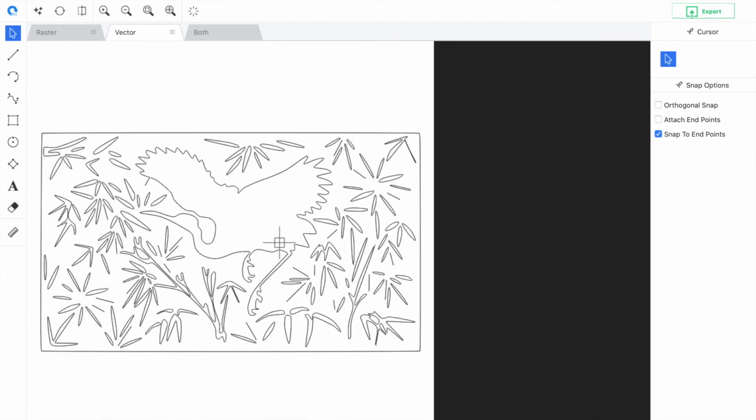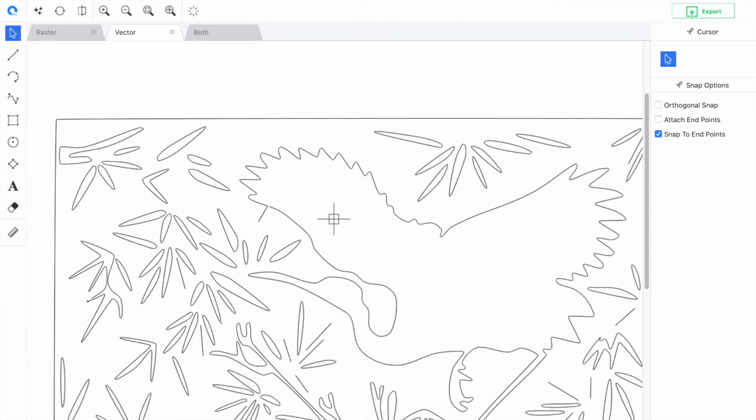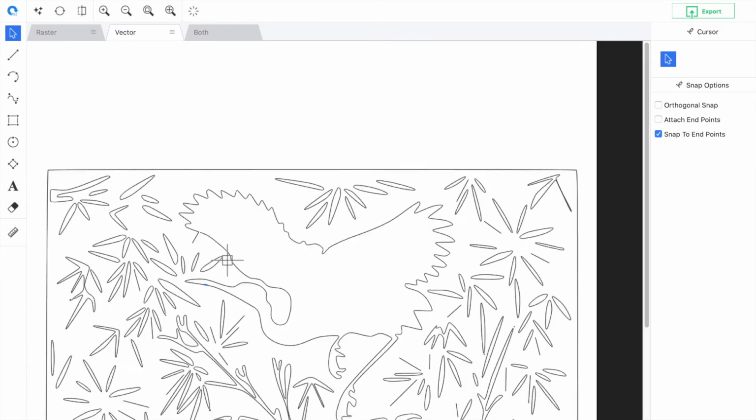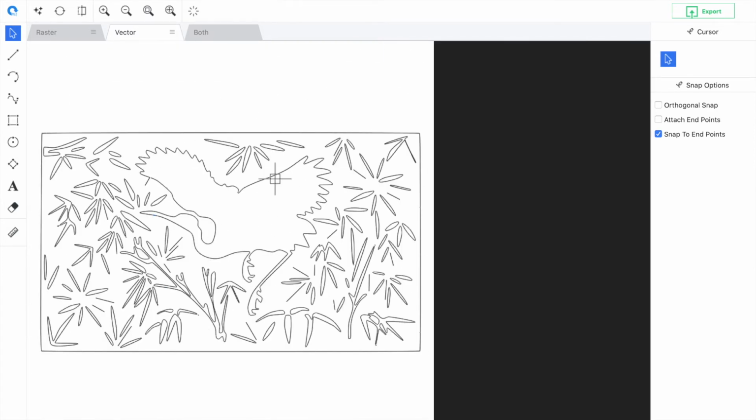The second problem is that if you don't have a fully optimized design with as few vectors as possible, it's going to look really ugly if you scale it up. So you can see again that this curved section here is formed of many vectors. If you were to scale that up, it wouldn't be curved. You'd have jagged shapes representing this. So again, that's a problem. Luckily, ScanCAD has CNC Smoothing, which is a tool to reduce the vectors, making it suitable for CNC cutting.